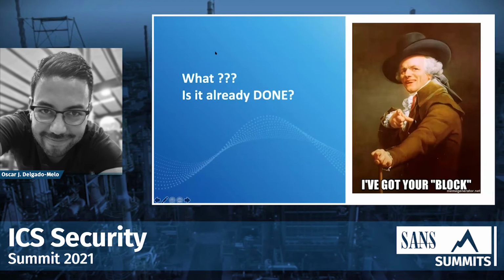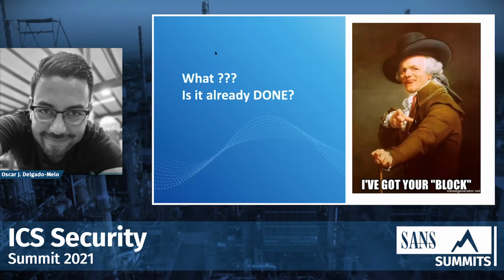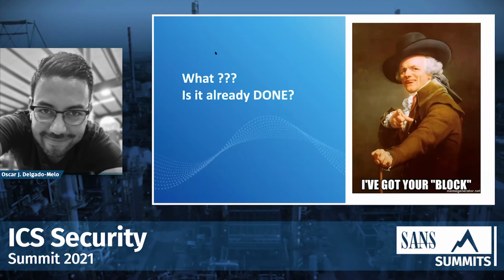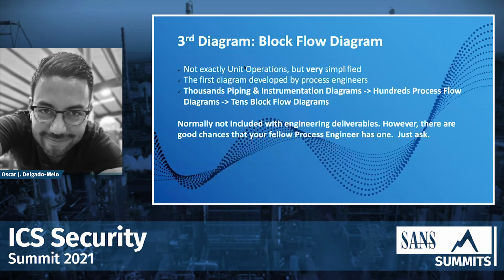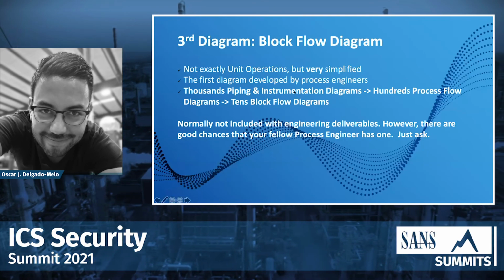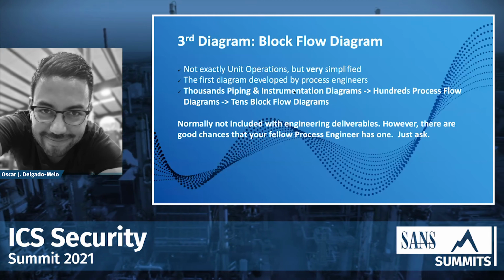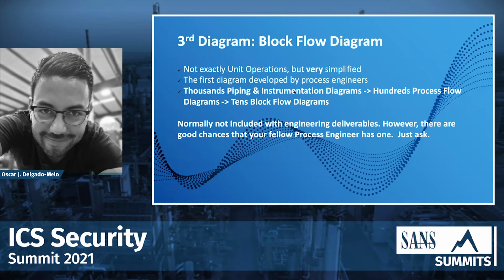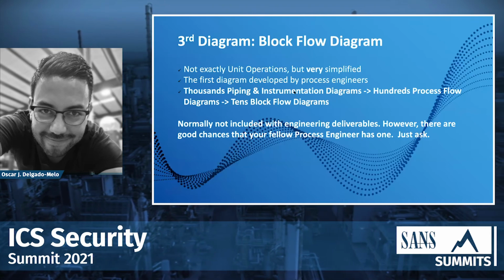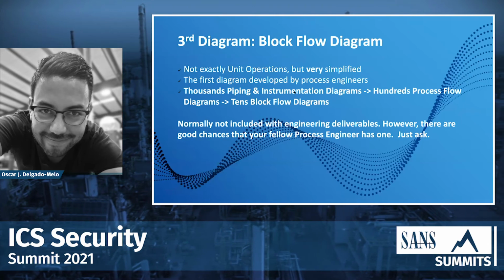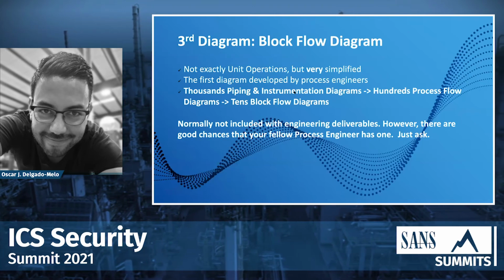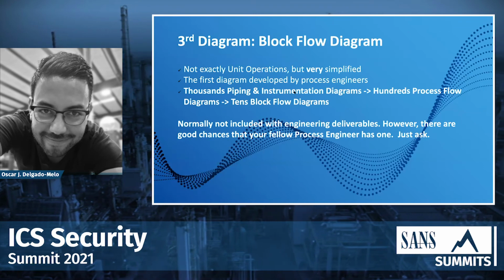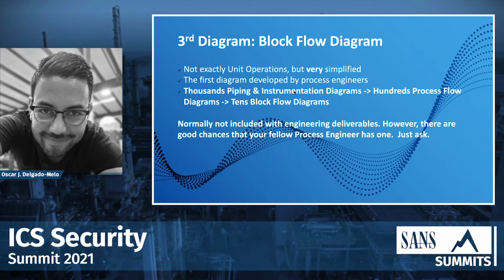So I just showed you how to do those analyses, but the good news is that most of the time you don't need to do it. You only need to ask for it. What I was doing is using this concept of unit operations to show something that is very common for process engineers, but not very common for the other disciplines, and that is the block flow diagram. With a block flow diagram, we don't want the details and all the specifications of the units. What we want to see is the whole picture, what is going on at a very high level.